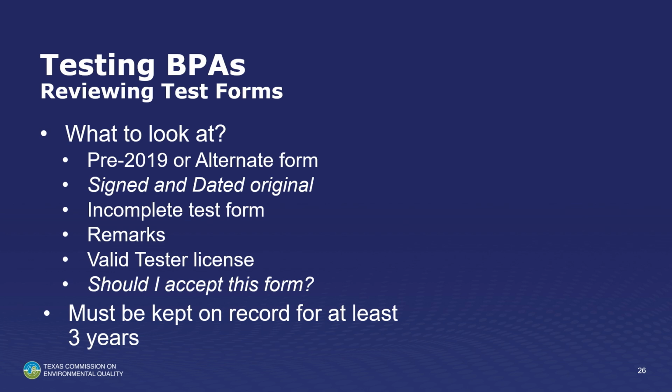Remarks. Most BPAT forms, you want to put a remark. If you failed it, you want to put what you failed it on, and what you're going to do to repair it. If you repaired it, you want to put what you did. Only use OEM parts in those out there. Only. Do not repair one with something from Home Depot. No, no, no. Could have lead, could have stuff. So go with a proper manufacturer there. If I'm working on a watch, I'm only going to use OEM watch parts.